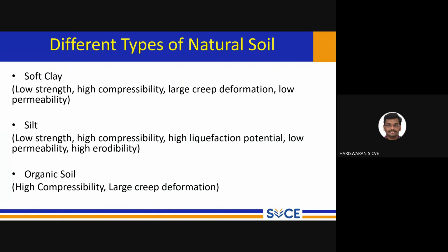Nothing will be visible. After 3 years, you are able to visualize the actual problem. Most of the problem we are facing is called differential settlement. A crack will propagate from the wall towards the top. That is the most important sign. We have to take care of some repair work to avoid a future problem.